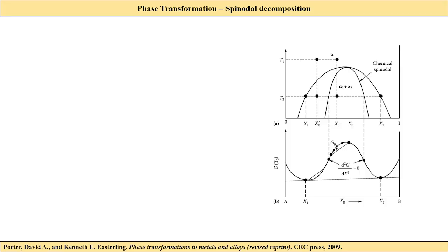For example, we have seen in steel, the famous example of the eutectoid composition, where gamma at 0.8% carbon, when it is equilibrium cooled from above 1000 degrees centigrade to room temperature, you will find pearlite, which is alpha Fe, or alpha ferrite, plus Fe3C, which is cementite.